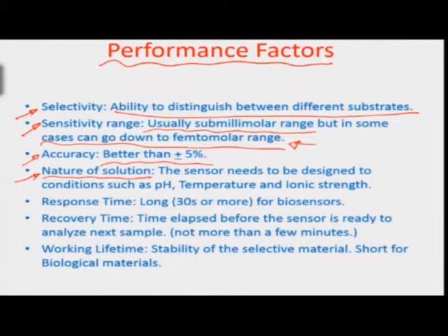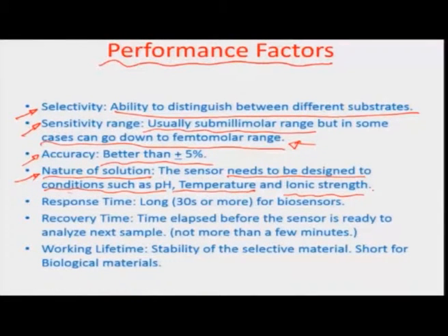Sensors need to be designed for the chemical reactivity, the conditions such as pH, for example, the amount of abrasion that will happen. So, the sensor needs to take care of that issue, so that the transducer does not dissolve away into the solution. It also takes care of issues like what could be the temperature range at which the performance or the functionality of the transducer does not change, or for example, what is going to be the ionic strength which is going to measure. Performance factors will also include a very important aspect which is about the response time.